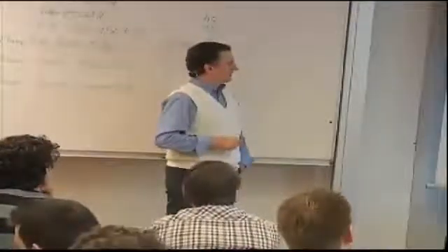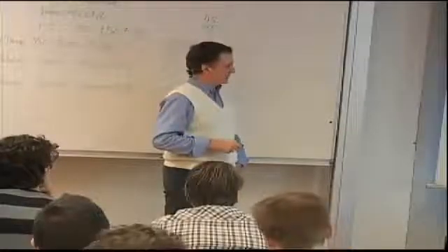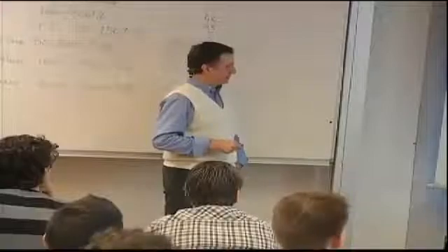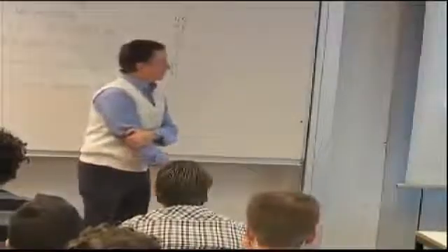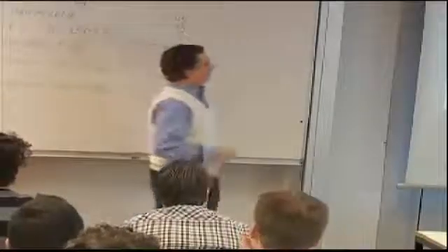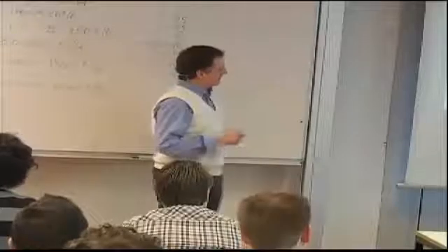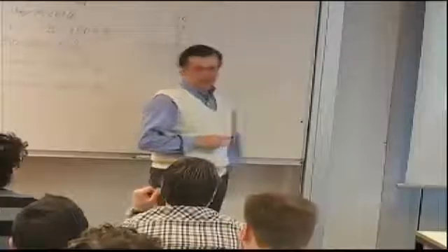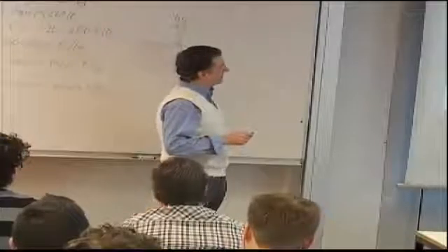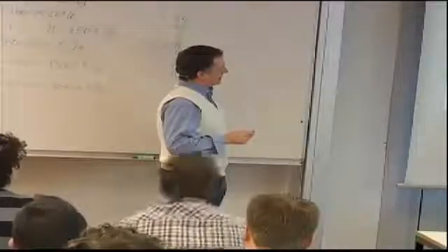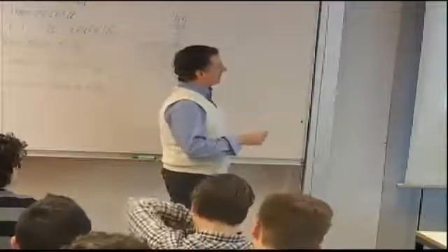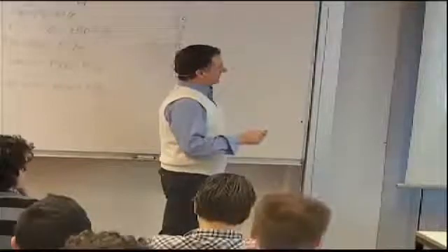And you have therefore 17 equations in 17 unknowns: the 3 displacements, the 6 forces and moments, and the 2 out-of-plane shear forces, and then the 6 strains, 3 strains and 3 curvatures. So the whole idea is to solve those, and if you eliminate as many of the unknowns as you can, you will arrive at the 3 governing equations of anisotropic elasticity in terms of displacements U, V, and W. And these are coupled because of the B matrix. You see that the B matrix here is always multiplied in this equation by W. So what would otherwise have been an equation involving only U and V picks up W here.